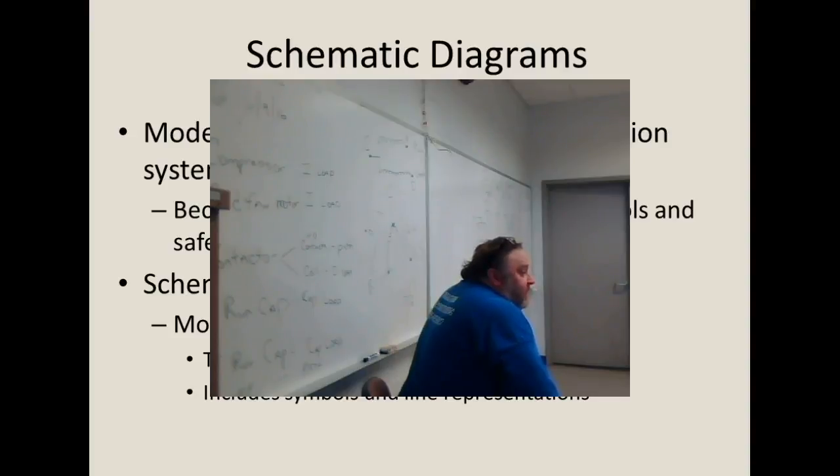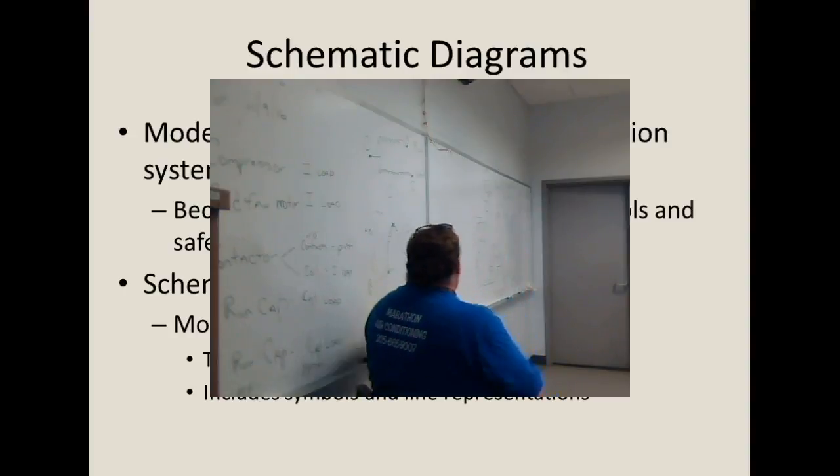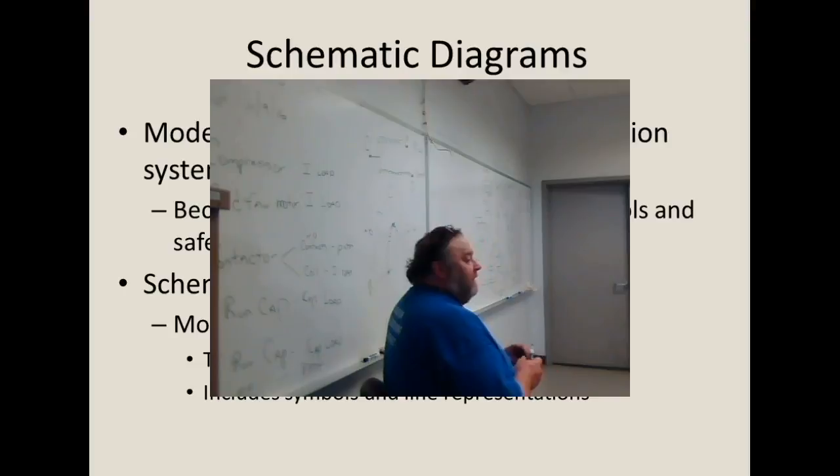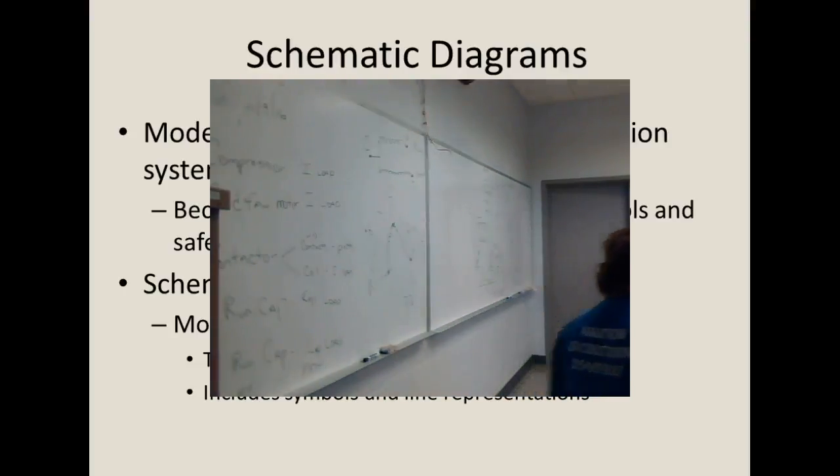Okay? The only thing that means it's good is what? MR, measurable resistance. 3.2, that's a measurable resistance. 0.6, that's a measurable resistance. See what I'm saying? But OL or 0, not any good.